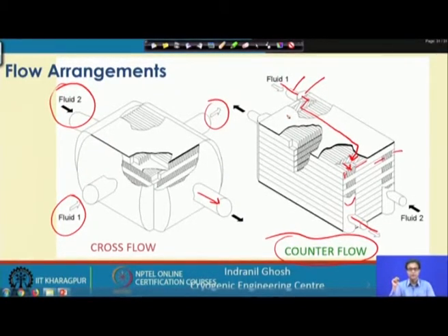So, while fabricating this kind of exchangers, we need to concentrate on quite a few things, and one of them is the fin. We need separating plates, we need headers, we need the sidebars, we need the cap sheets. Cap sheets are the top cover and the bottom cover, and of course the header and the nozzles. And in case of a counter current exchanger, we need appropriate distributor fins on each side and each layer.